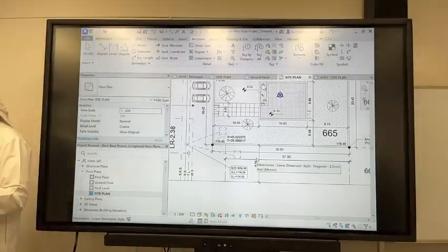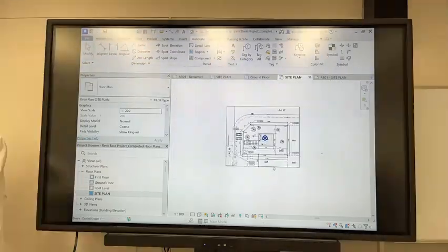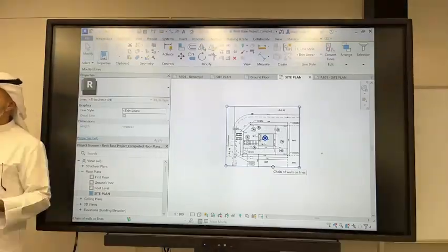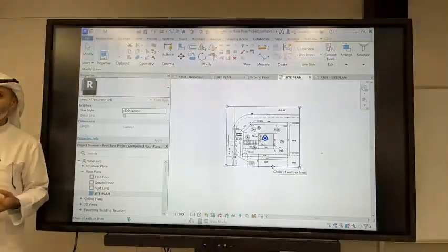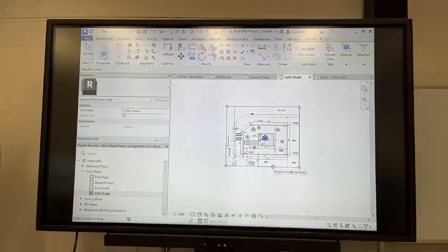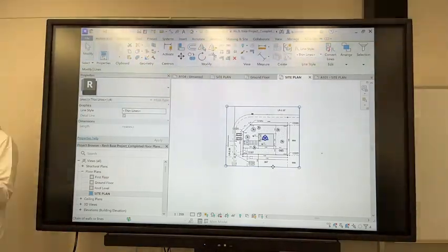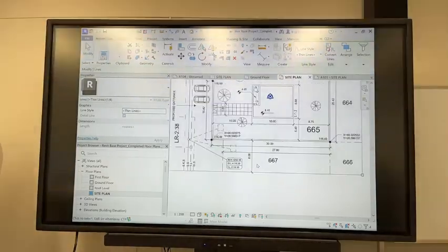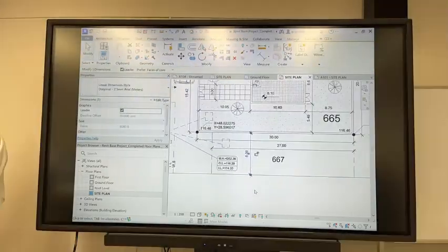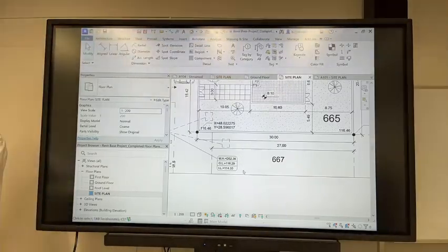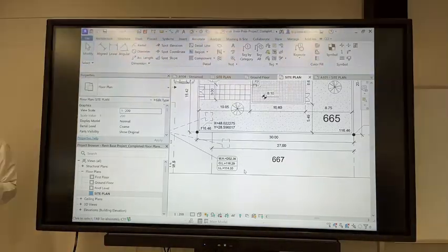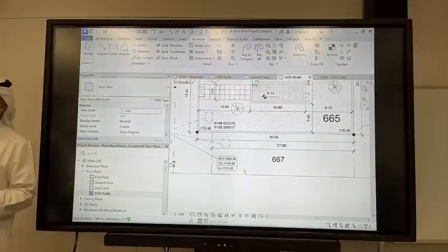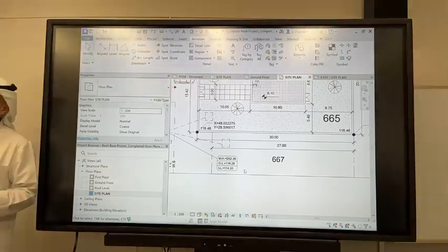Okay? Well, I did a border in here, which is cutting off the context. The street across, my other neighbor, top, right, they're not showing. I can't put a dimension just because it's within my border. This is the dimension. So you have two things to do. Either you remove the dimension, which is fine, or you insert it manually. Write 22 meters, which is the plot width. So two things, but don't put something that doesn't make sense.